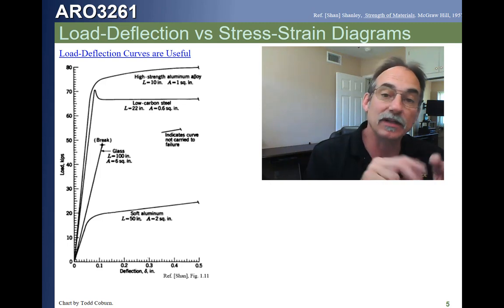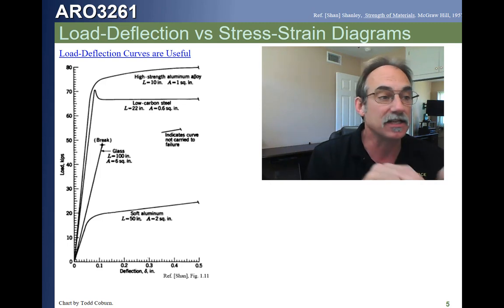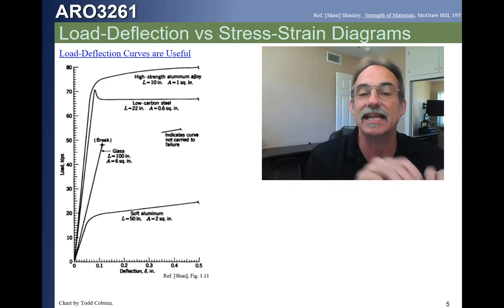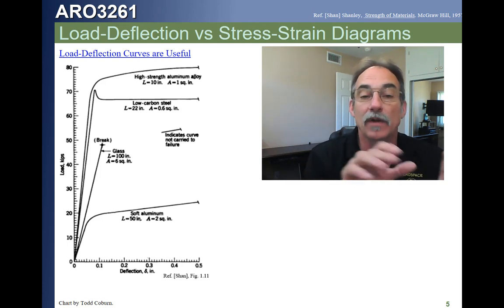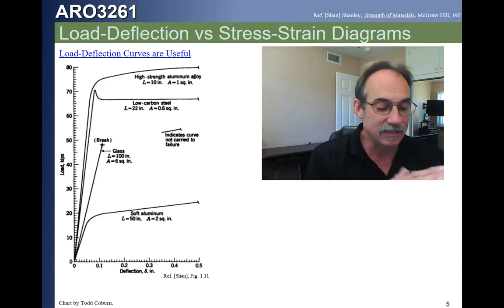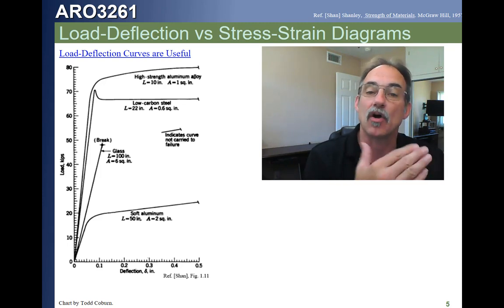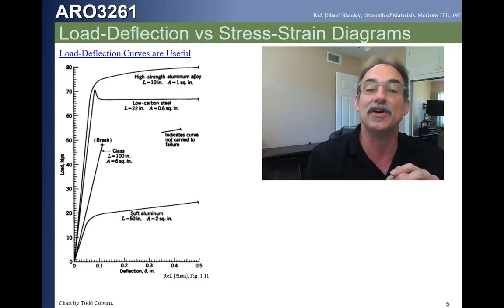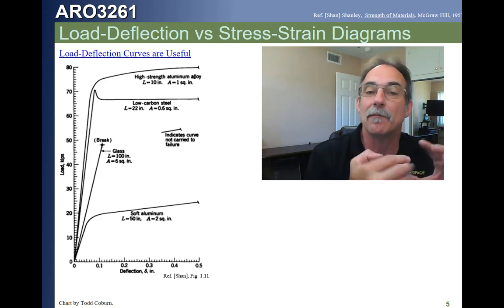We're going to look at a formal definition of stress in a minute, but basically force divided by area is stress in its most basic form. What that means is, since it's the force per unit area, we could call it a force intensity. I haven't ever heard anybody call it that, but we could, because that's really what it is. So we divide the force by the area.